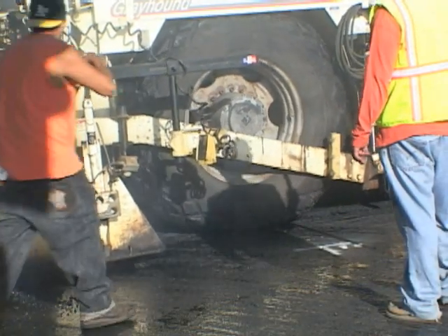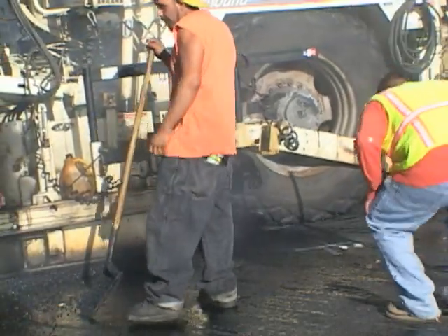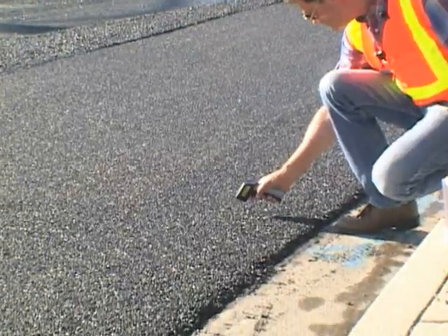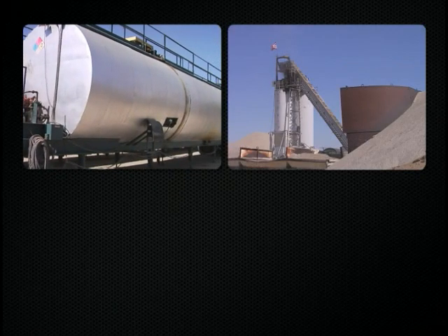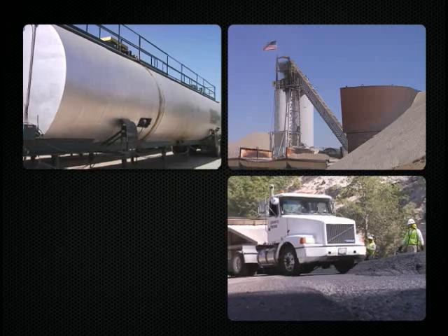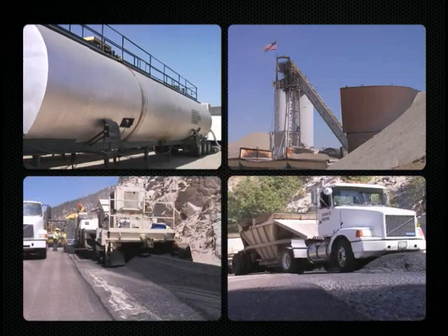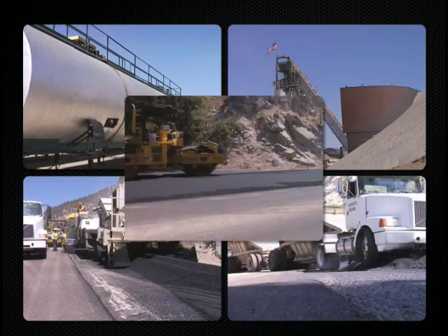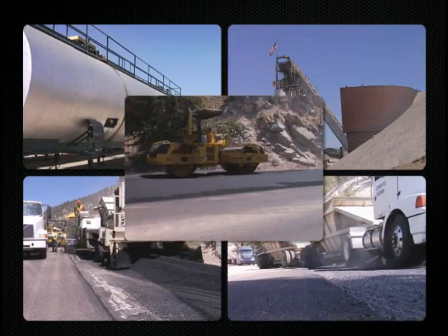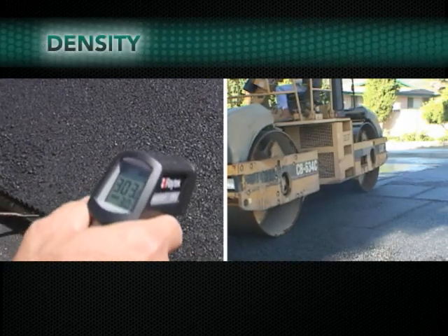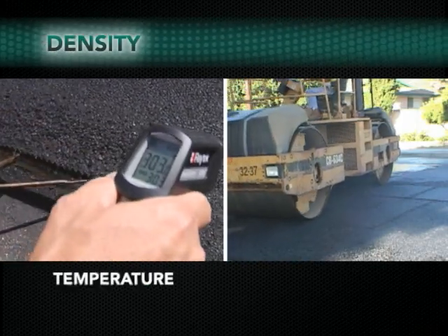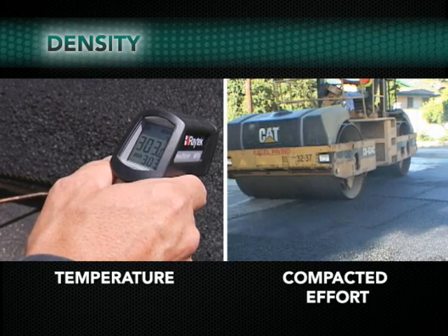Good practices for conventional HMA placement shall be adopted. Special attention should be paid to temperature management. Coordination of the binder production, mix production, mix delivery, placement of material, and compaction are essential to provide for the service design life of the pavement. In short, density is controlled by the material temperature and compaction effort.